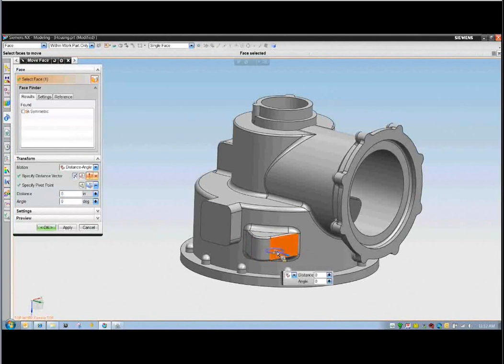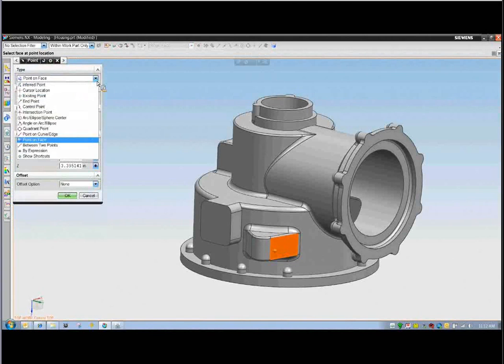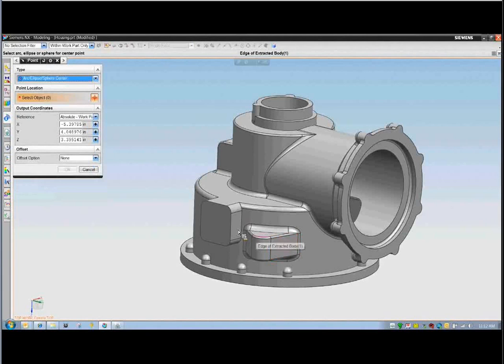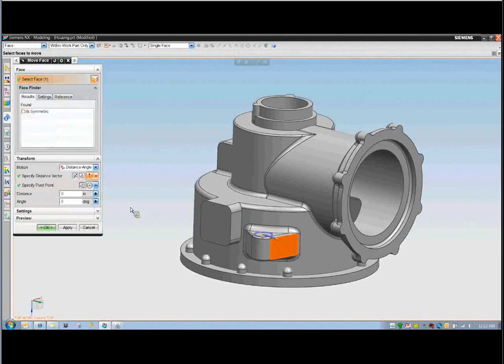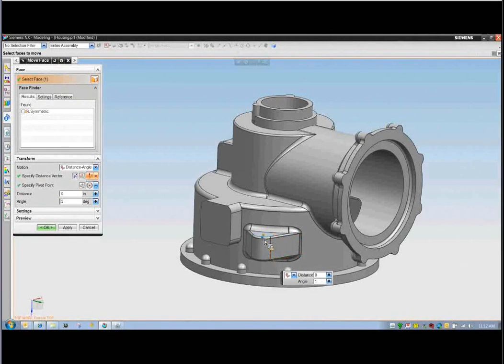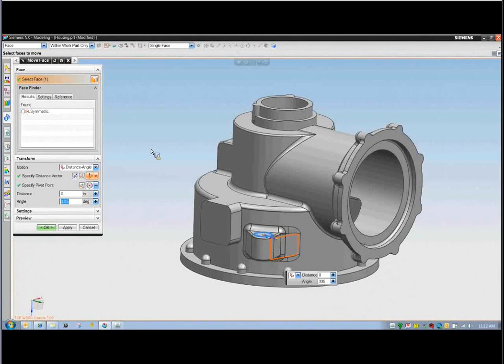Let's select this face here, and this time I want to actually revolve this face, but I want it revolved around the center of this arc here. And now I can select this pull handle, and you can see from my preview, I'm doing really an incredible amount of editing on here because it's maintaining all the blends, all the tangencies that were in there.